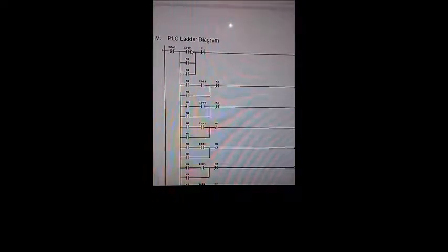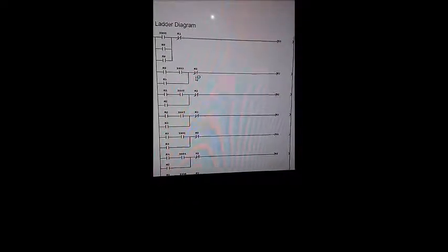X1 is represented as the stop button and X2 is the start. It will continue as a loop to M1, going to a relay to M0, opening, closing the M0, and proceeding to the next bracket that will produce M1, 2, 3, 4, and so on and so forth. This is the input part of the table, and next this is the Y version,